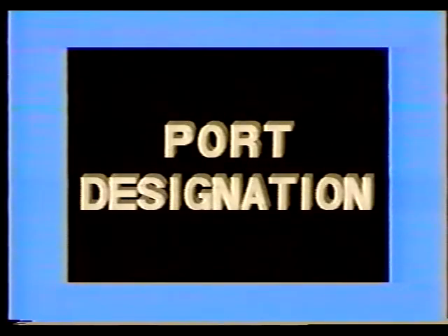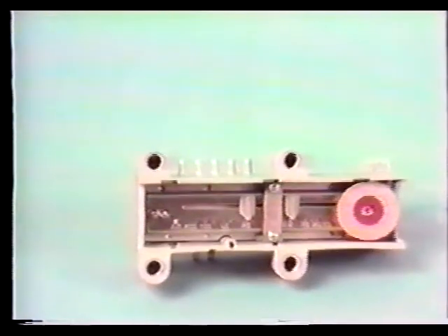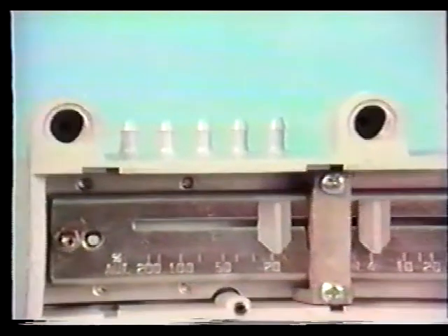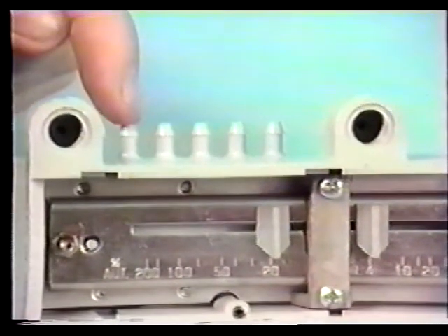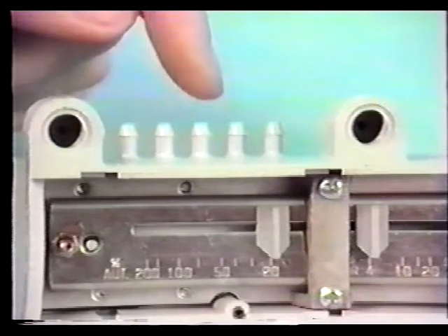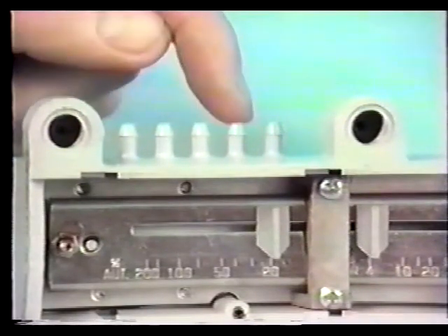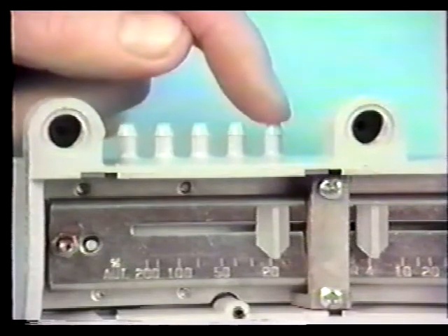Receiver controllers of different manufacturers utilize different port designations. This is a 2341-001 model made by Robert Shaw. Port designations on this device are: 1 for the primary input, 2 for the remote set point adjustment, 3 for the secondary or reset input, M for main air, and B for the branch line output.